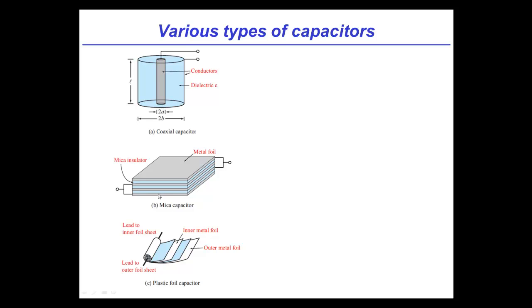Now, capacitors are often, here's an example of a mica capacitor, but really what I'm about to talk about extends to many different materials. Very often what you do is you build these composites that are laminated stacks of metal, then insulator, then metal, then insulator, and the alternating metals are shorted together so that they form one giant terminal. So this just looks like a bunch of parallel plate capacitors connected in parallel, effectively. That's exactly what they are. They're interdigitated with each other, and they're shorted so that they alternate.